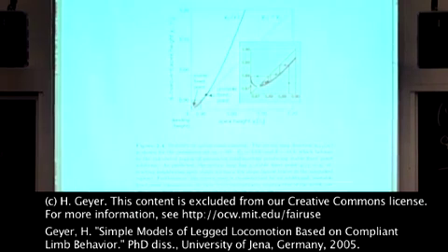But then looking at this again, now here's another strange thing. It looks like it should be globally stable then, right? Because if in practice we can't get above that unstable fixed point, and if you look at this apex axis, the higher it is, the slower it moves. So at your minimum apex height, that's when you're moving fastest. It looks like it's stable throughout the entire operating regime, right? The fastest it can move is that little guy on the far left, where it's apparently stable. And the slowest it can move is this vertical bouncing, that unstable fixed point. So how do you explain that?